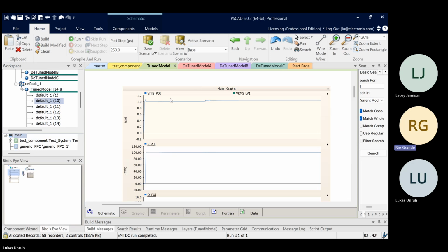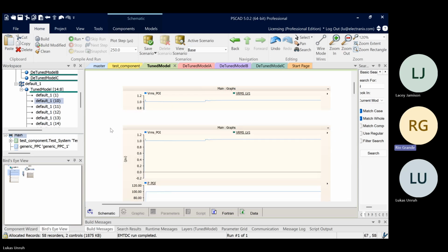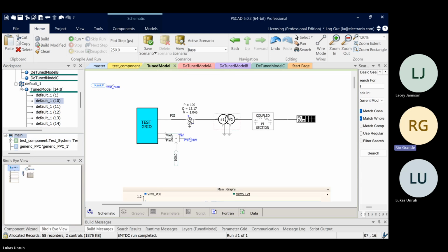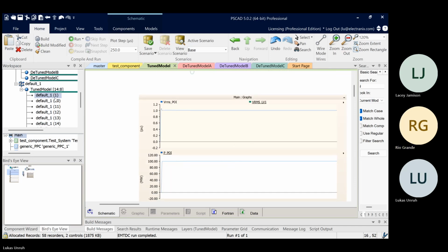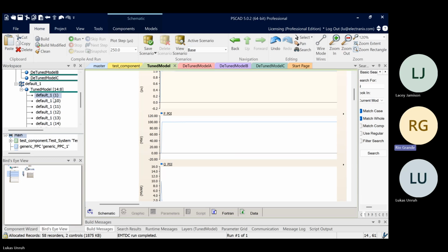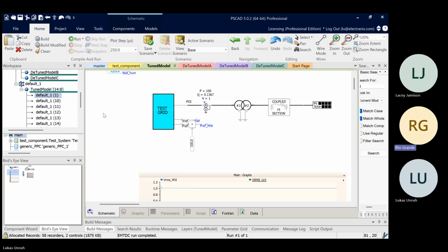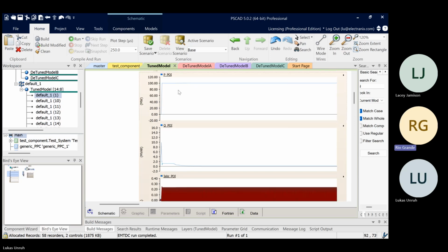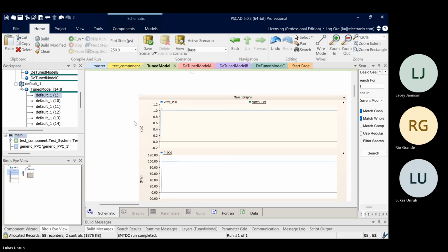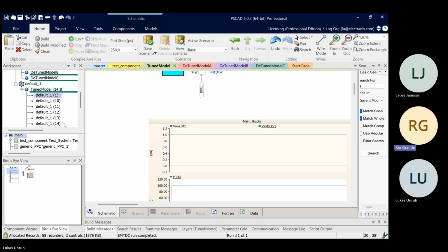But if you have a detailed model with perhaps multiple IBRs in here, and the actual switching models or whatever, then these tests can actually take quite a bit of time to run. So that computational time can definitely be significant. So this test 1 was just a flat run, I think. So we're getting to a max of 100 megawatts, and you can check your Q. Should be around 0 for this test, given just for this specific system strength.